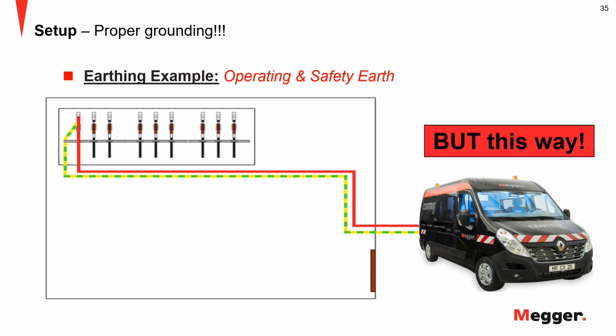Then you minimize the antenna effect. And remember, the coupler is very close to the termination where you connect, very close to the connection point. So the IEC filtering that the coupler can do, that is okay. You can suppress any kind of noise there, and you minimize the distance from the coupler to the connection point itself, a few meters of cable where you can have any kind of interference being picked up.